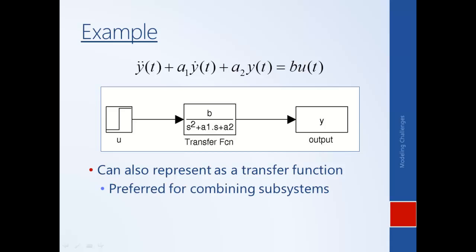And there are many nice things about transfer functions, one of them being that they're algebraic. So no derivatives, no integrals. It's only multiplication and division by s. They're nice for combining complicated systems, systems in series, for example. Unless, of course, you have loading in your system, then you need to be careful, as we talked about when we were modeling circuits.